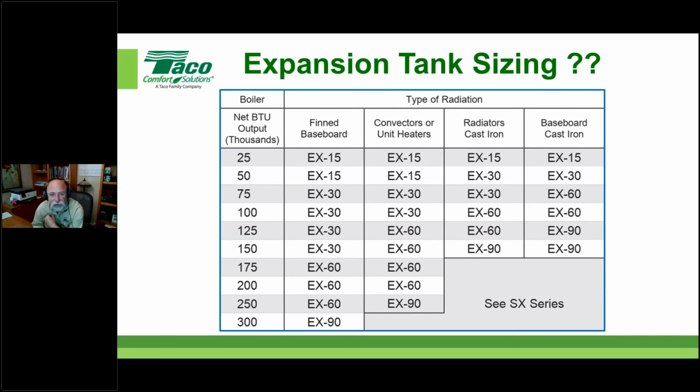And we're going to be teaching on that when we get into some understanding of the net suction pressure that's needed on these new ECMs, these bigger VR ECMs. It's important with every circulator, but when we start talking about wet rotor circulators, it's very important to not have the fluid boil inside the can, being the portion of the wet rotor assembly. That's even more important in those smaller applications than it is about getting little pellets in our impeller holes, tearing things up. So anyway, we'll save that for another teaching. Okay, how important that is.